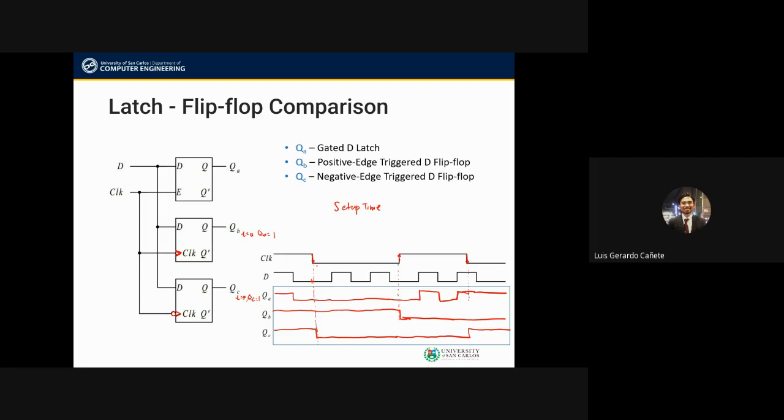Now that depends on the manufacturer. It depends on the type of technology that's used. If it's low power Schottky, or if it's CMOS, if it's high speed CMOS, these things change. So you need to look at that using data sheets and data books. And most manufacturers will write that down. So yeah, this is quite important, okay?